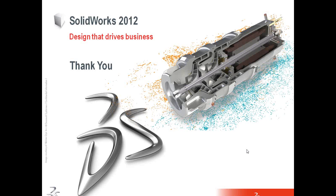Yeah, there's one more question about exploded view. You can definitely get an exploded view in the view palette. It is automatically populated in the view palette. You don't have to do anything in 2012. Previously, you had to drag an isometric view into the drawing, right click, go to properties and select show in exploded state. But in 2012, if you refresh the view palette and there is an exploded view in your assembly, SolidWorks will automatically detect it and create an isometric exploded view in your view palette in the drawing, and then you can just drag and drop it onto your drawing.